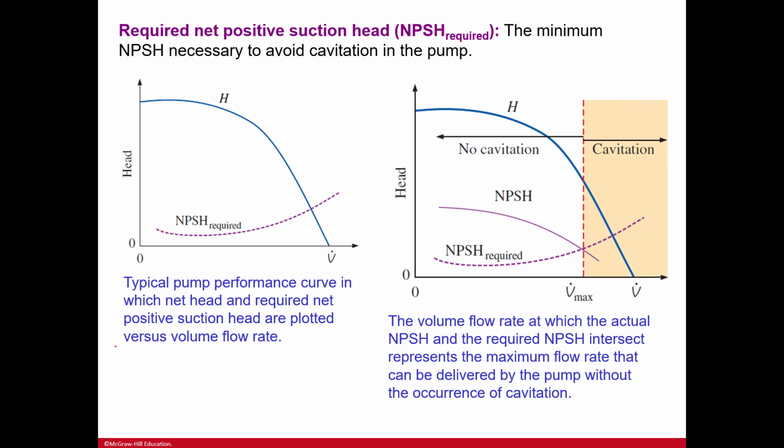So you do have a required net positive suction head. It's the minimum net positive suction head necessary to avoid cavitation in the pump. So it's what you have to avoid that cavitation.